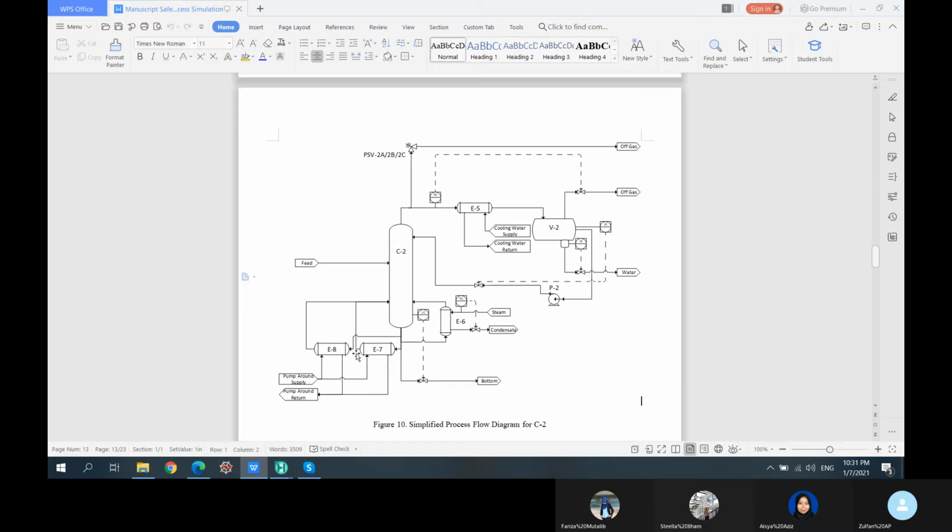And there's also typically the fire case, where we have a fire somewhere, and this fire gives heat radiation to the liquids in the reboiler and the adjacent equipment. So it will be vaporized and go up the column and pressurize it, which has to be released. So there are many scenarios, and each of them will have a different load to release.